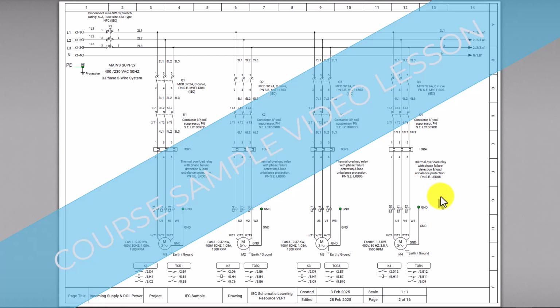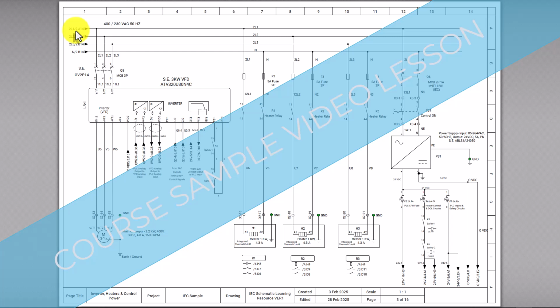If I go to the next page, same layout, power across the top, and then all of the devices. In the case of this inverter, it is tapped off the 3-phase power. And then you'll notice that we have single phase devices. So each one of these are heaters. They tap off of one conductor and the neutral. And then at that point, you can break the neutral through these relays, these heating relay controllers. You'll notice that it's breaking each one of those wires.